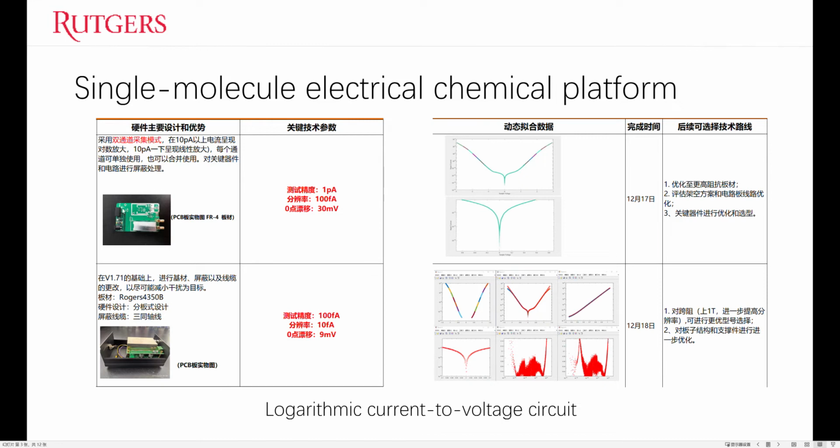Then I improved this PCB, and it became the second one. I put the power supply under the measurement circuit and held the measurement circuit in the middle of the box, so it can improve the noise shielding a lot.